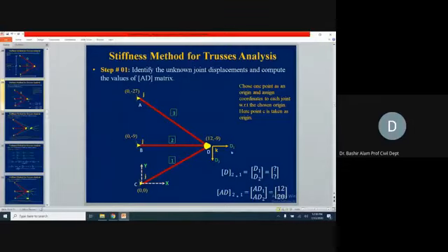So we have fixed now the joint coordinates. Now, remember, you can take out your pen now. This B was your origin. Then how do we fix our joint coordinates? Very simple. B will become 0, 0. This will become 0, minus 18. And this joint C will become 0, plus 9. And here, this will become 12 and 0. So accordingly, from this origin, you can find out the rest of the coordinates.